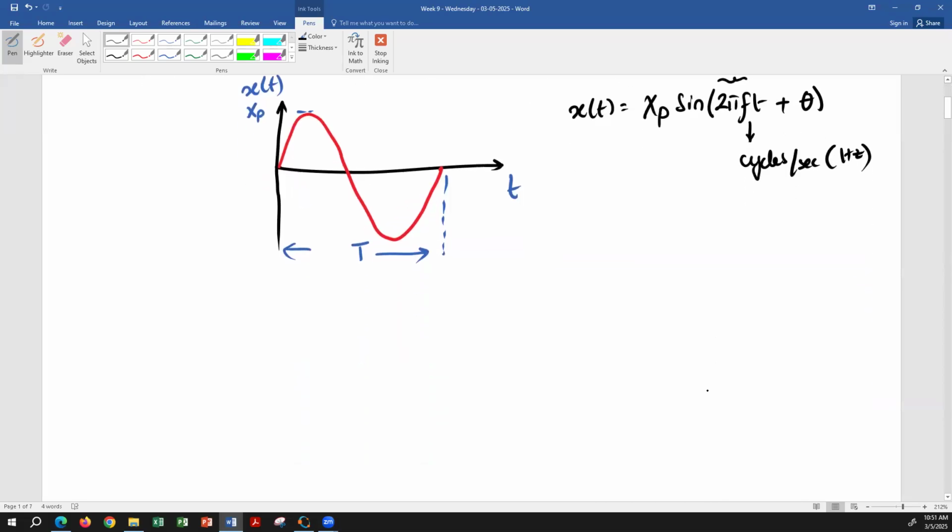The steady state analysis is not done in the time domain. Why? Because integral differential equations are hard to solve in the time domain. Anytime you have capacitors or inductors, you are solving integral differential equations, because the voltage and current of a capacitor and inductor are related by a differential equation. We just discussed the second order RLC circuit and the first order RL and RC circuits. But if you have more capacitors and inductors, then the equations in the time domain become very complicated to solve.